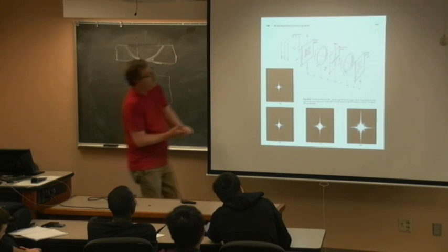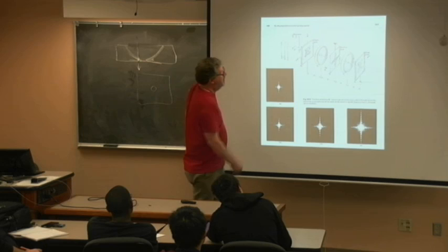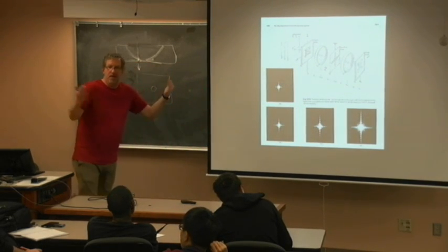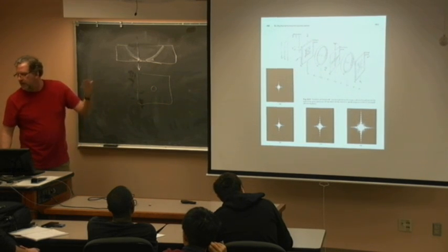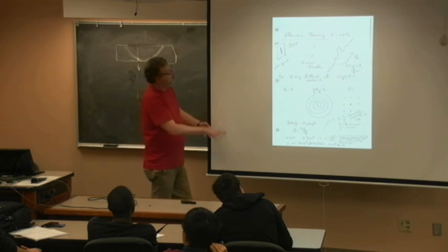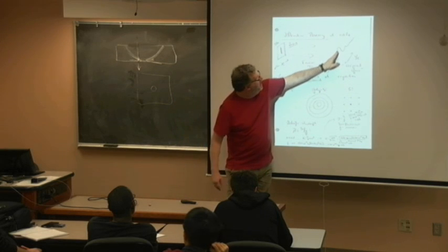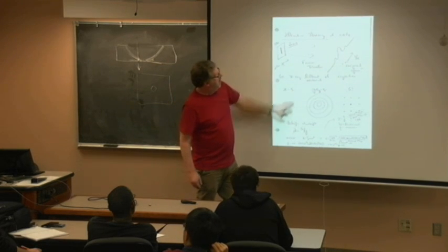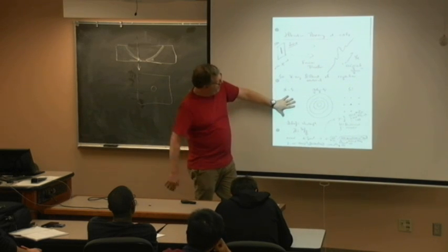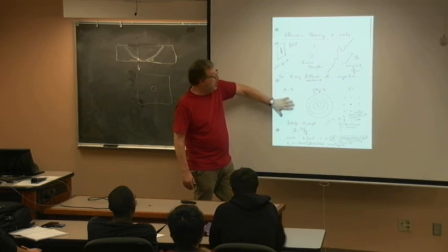So the diffraction pattern will tell me the crystallography of the specimen I'm inspecting, and then the image plane is where I actually see the transistor, the device, the solar cell, the photodiode, the LED, whatever. Just like I'm sending light through a slit, which as you saw before, that sin x over x kind of thing was the Fourier transform. If I do the diffraction through amorphous material, it's going to be completely scrambled because the diffraction is going to be completely random. So I'm just going to get a blur.